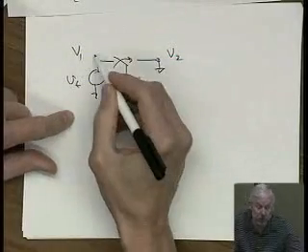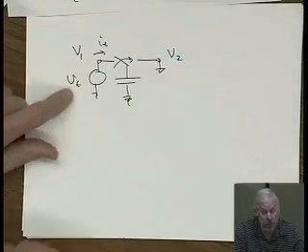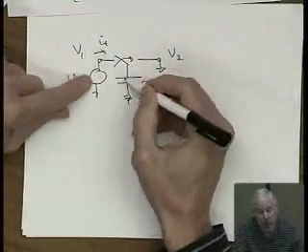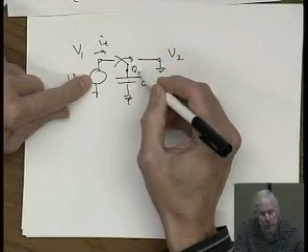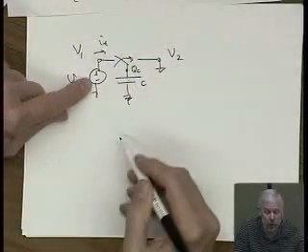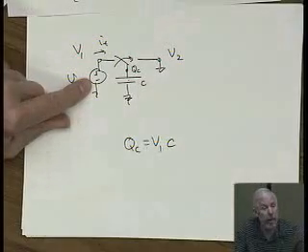Let's figure out what current goes into this circuit. When this capacitor is on this side, it charges up. We have to look at the charge on this node, Q on C. This is a really different kind of thinking. The charge on this node is QC, and it's equal to V1 times this capacitance value.